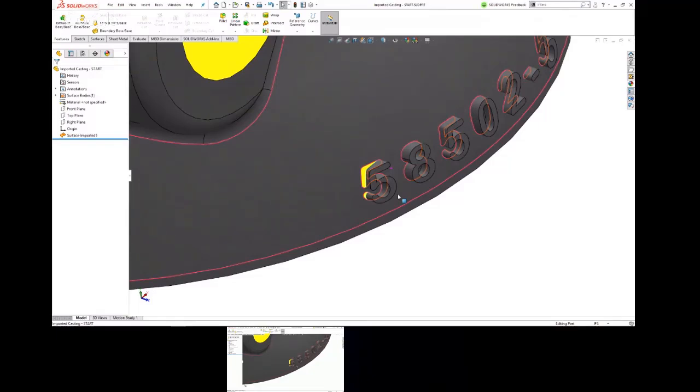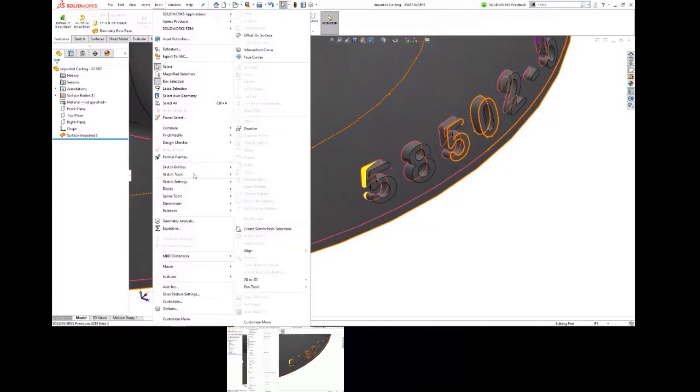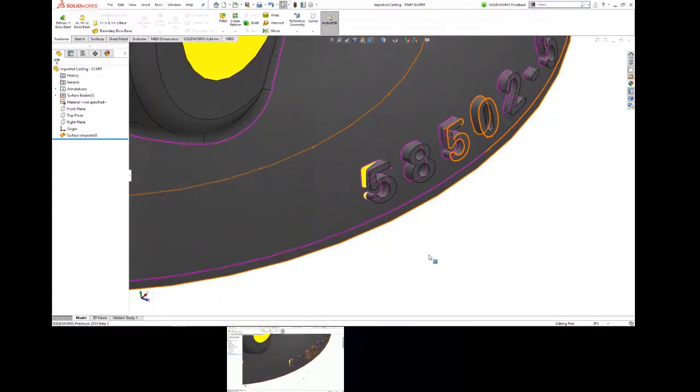Yeah. All right, so we want to clean up this geometry, and I just want to try to avoid a hack and fill type approach as much as possible. So if that text was on the inside of the part, is there an easy way to highlight where the problem is? Then it becomes a little trickier. You can use the tools check command. Well, in fact, if that's a casting, tools check will show you where you have open surfaces, and it would highlight those for you.